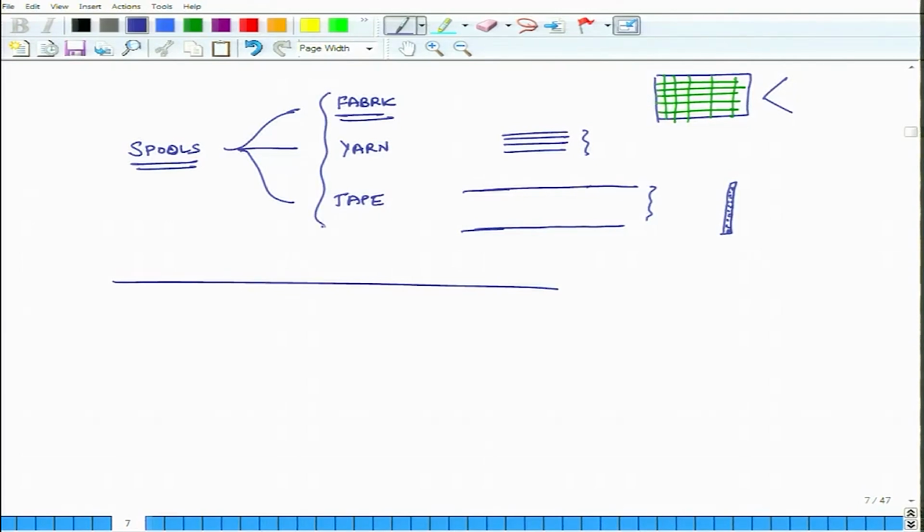We have already talked about sizes, and we have also talked about coupling agents. Okay. So, once the fiber comes to the place where it is being used to make a composite, you have to remove the size. Okay? For instance, if you have starch which is covering the fiber, starch by itself can absorb a lot of moisture. So, that will make things bad. So, first you have to remove the size.